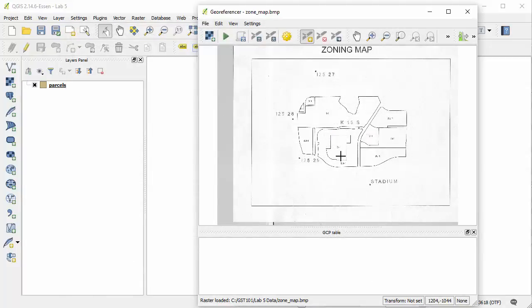The source data we're looking at here is a map. On this map there are 5 points with their associated names. So here, here, here, here, and here. These are benchmarks maintained by the United States National Geodetic Survey. To georeference the scanned map, we will create control points at these 5 locations. The plugin will then develop a georeferencing equation based off the set of source and target coordinates at these 5 locations.